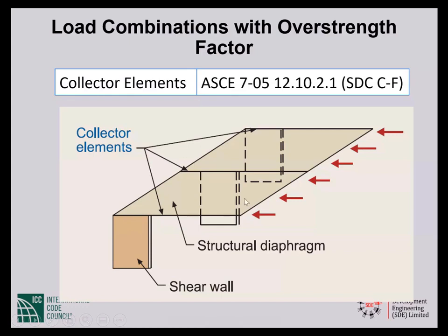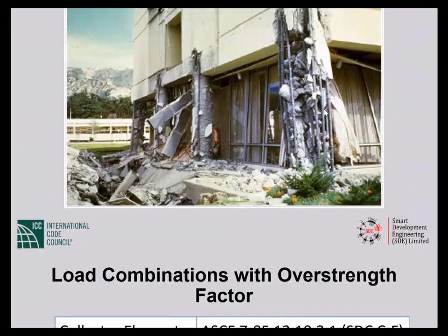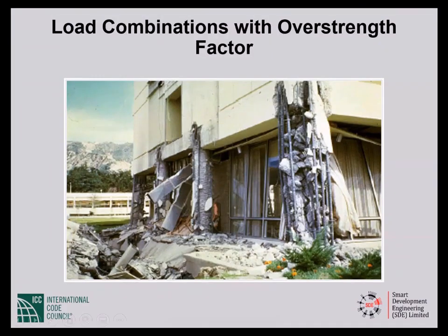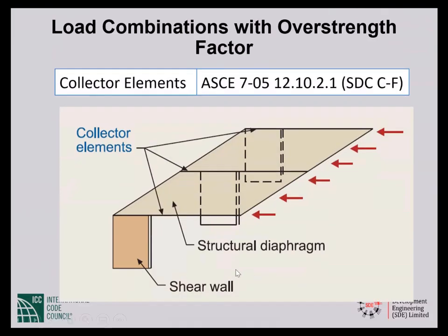Now, this diaphragm under that lateral load develops shear forces along the parallel edges. Okay, this face develops tension, that face develops compression, and the parallel faces develop shear.